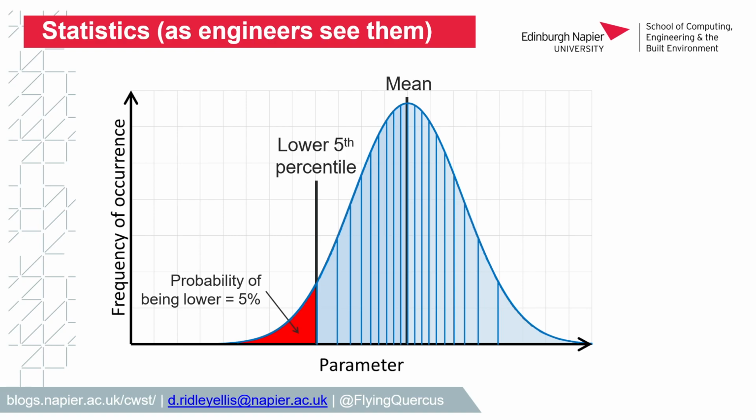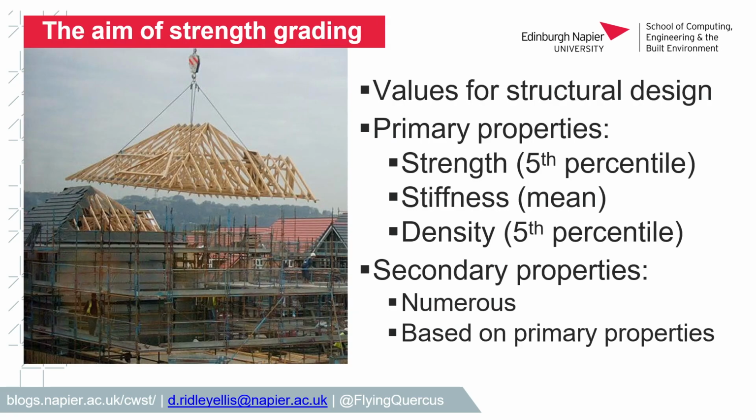Now, here's the thing: when you design something, you never design anything with one connection, and you never design a floor cassette with only one joist. Never do that. When you design a beam or a lintel, that's something slightly different. You're specifying a much higher grade to start with, C24, or an engineered wood product, which has a much better chance of never failing. Using a floor cassette, 5% of the samples will be lower than that, but the work is a system.